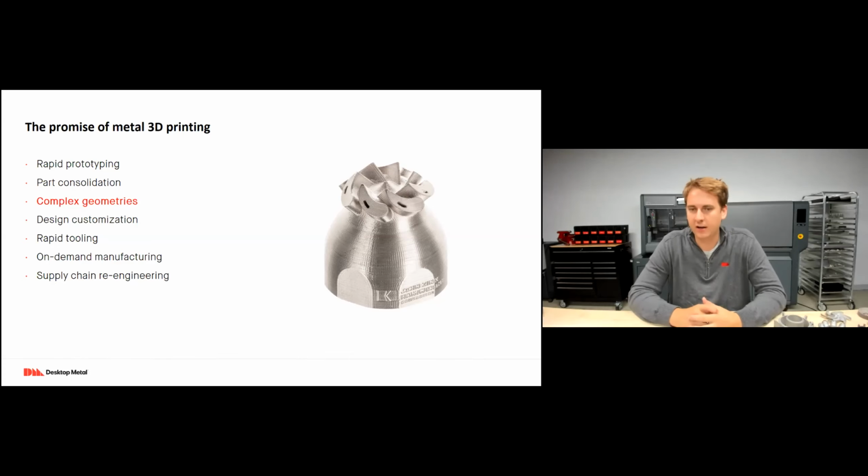With 3D printing, it's often possible to add complexity to your part that actually reduces your part cost and reduces the processing time. So you can imagine adding lightweighting features to a part. If we were machining that part, we now have more cuts, more material to remove. That's actually going to add to my part cost. It's going to add to the lead time on that part. It's a more difficult part to machine now.